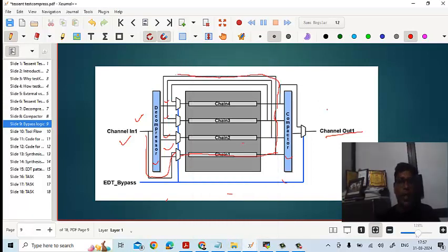So it comes over here, you could see this enters scan chain 2, and again chain 2 goes over here and then comes over here to chain 3. It's like a spiral loop. So it comes to scan chain 4 and finally it goes out. So what I mean to say is, with bypass, you will have only one chain.